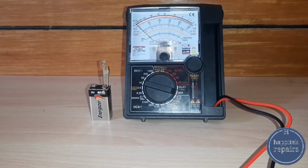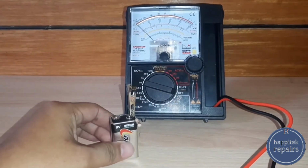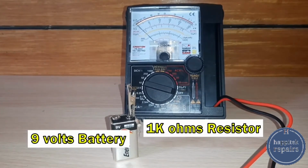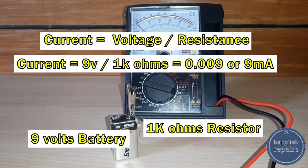Now, since we know how to read a multimeter scale, let's measure a resistor with a 9-volt battery. I have a 1k ohm resistor here. Let's measure it with a 9-volt battery. First, let's have a quick calculation using Ohm's law, that current is equal to voltage divided by resistance. Here, current equals 9 volts divided by 1k ohms, which is 0.009, or 9 milliampere.